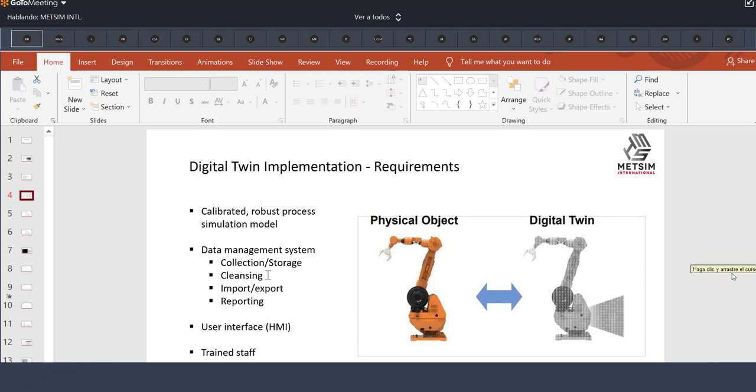Whatever the process may be for operating, within a digital twin you do impose limits where a value coming in should be between, I think I said, 15 and 20. It has to be within 15 and 20, otherwise the model will throw up a flag. And you can then have user interfaces available for alarms, information, things that pop up, completely customized. So I hope I answered your question there, breaking it down from top to bottom.